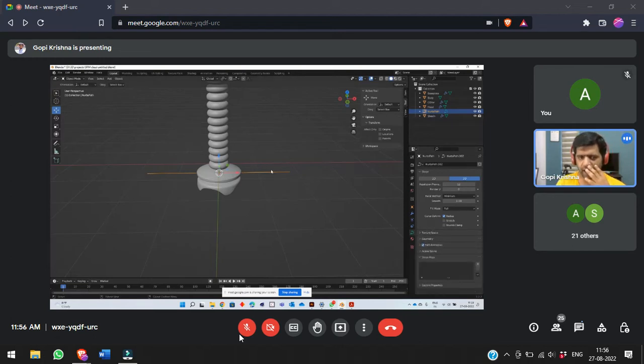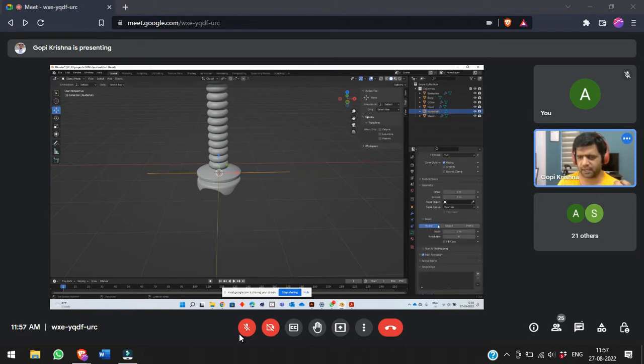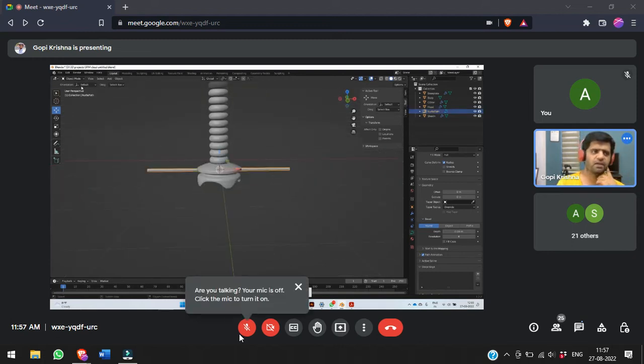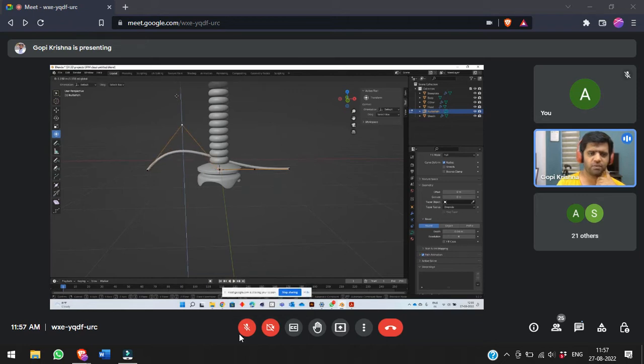So everything will be like this now. Now what we want to add is some geometry to this curve, if the curve doesn't have a geometry now. So I go to geometry, okay, and then there is a bevel. You increase the bevel width. You see, once you increase the bevel width, it will give some geometry to the curve. It's as simple as that. Now, if you go to edit mode for the curve, you can select something and you can move, and it can move a smooth curve.